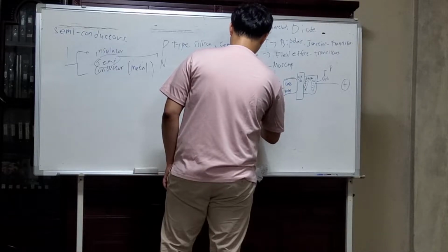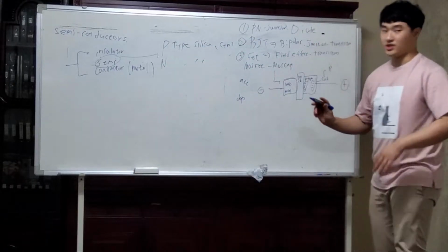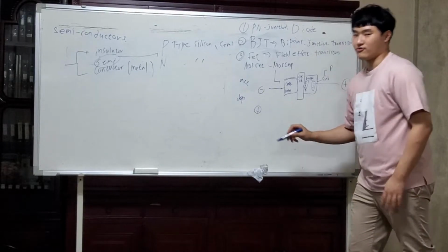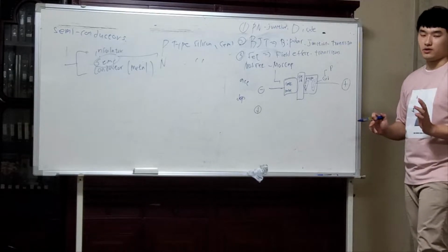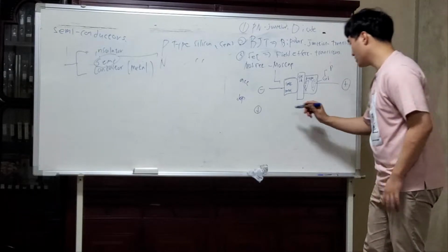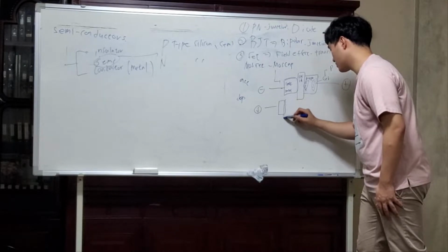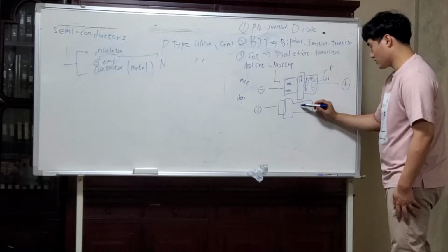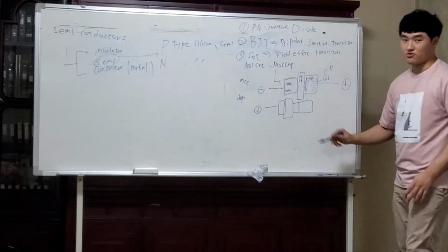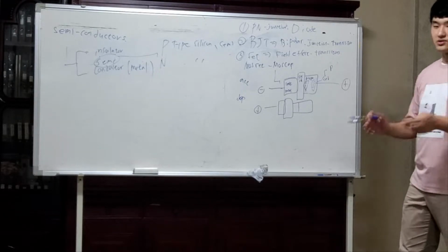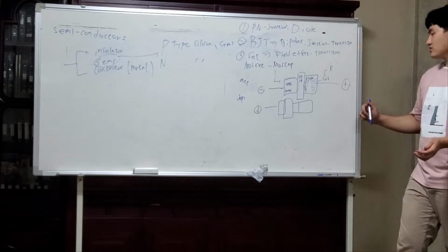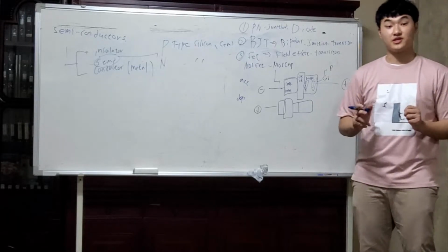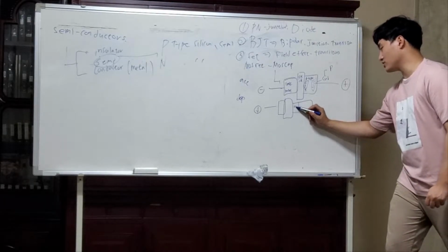The second, depletion. Now we change the applied voltage to a somewhat bigger voltage that doesn't exceed the threshold voltage. Then, by the force of the positive voltage, the carriers will not be present at the surface between the oxide and the substrate. So here we make the depletion region.